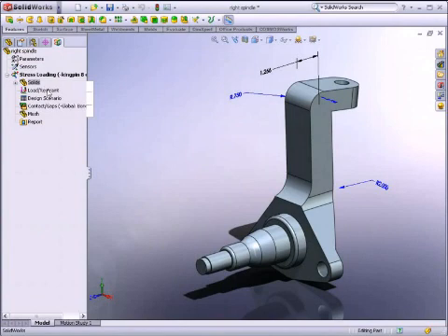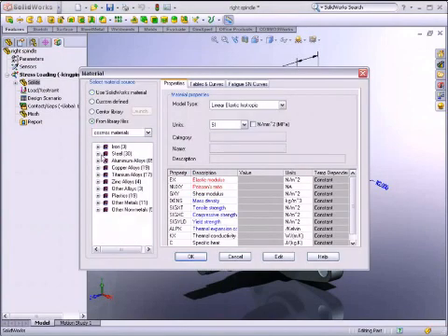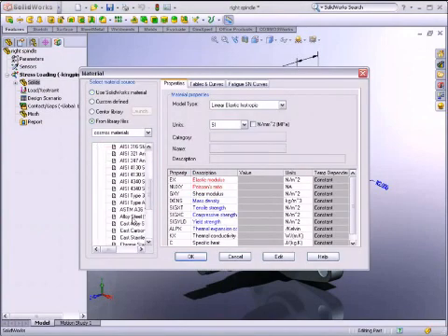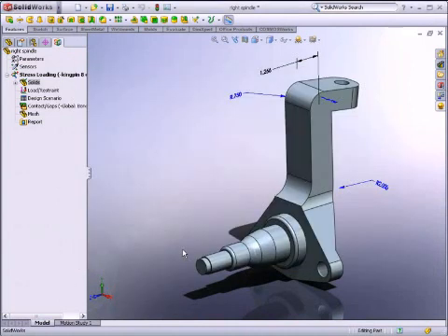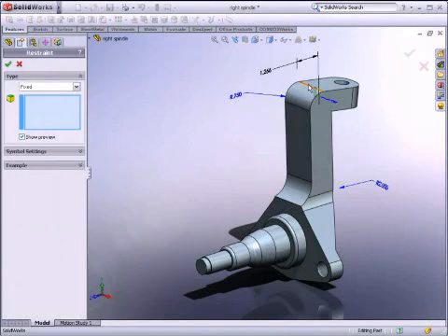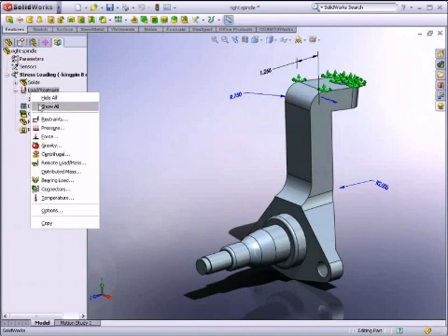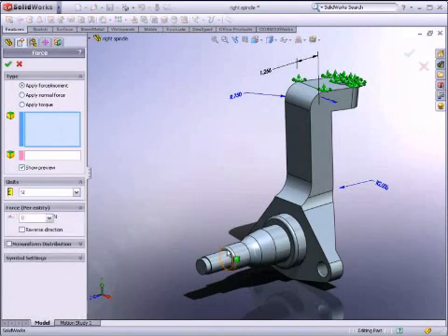weight. Because this part acts as the connection point between the controlling arms of the suspension and the wheels, the integrity of the design must be maintained. To determine the criteria for the optimization, you will apply a static loading study. Depending on the design, you could also obtain the design criteria by running a thermal, frequency, or buckling analysis.